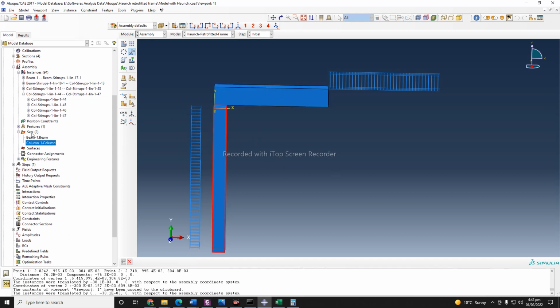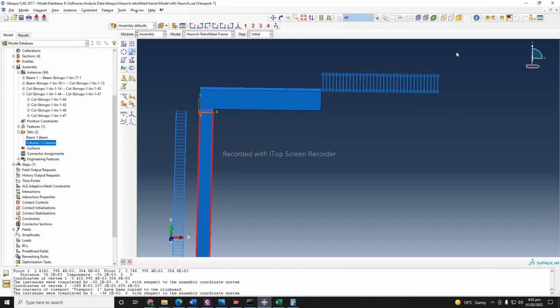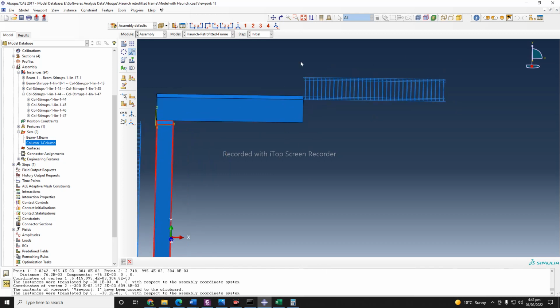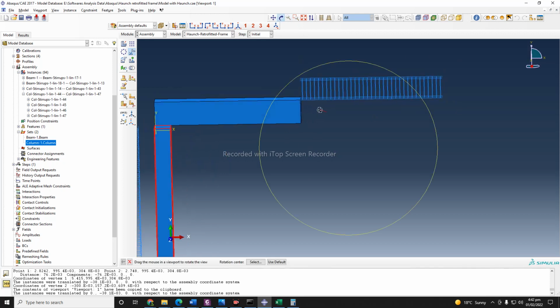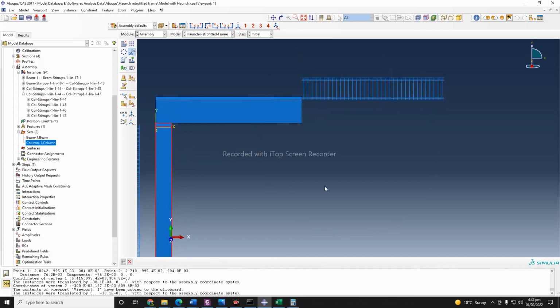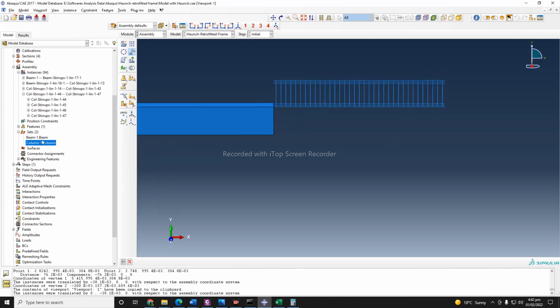Okay, so now I want to define the reinforcement of beam and the reinforcement of column as well in the set. Why? Because I will be needing those for my interaction surfaces when I will be embedding my rebar in the reinforced concrete. So at that moment I need to have a set of each instance separately. So it's a really good moment to have a set.